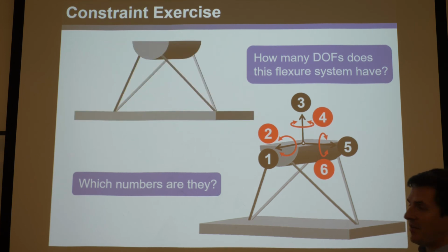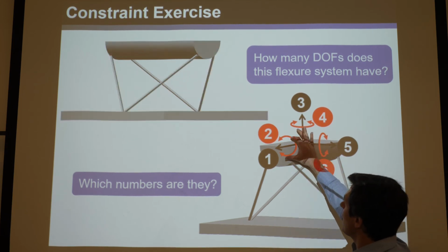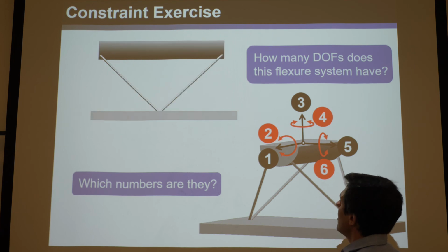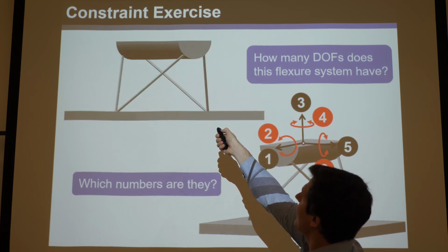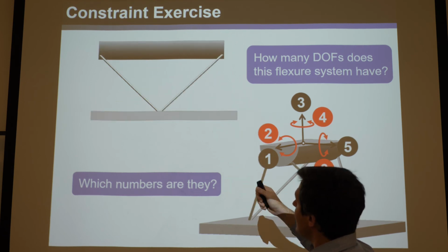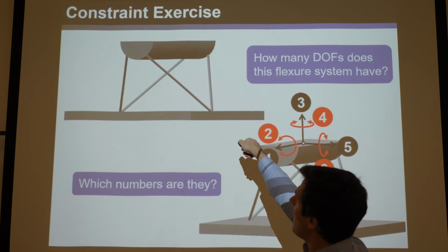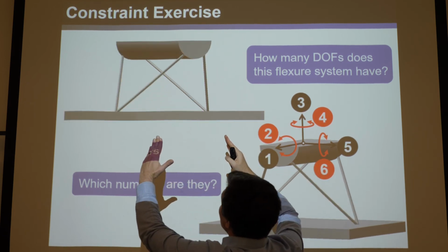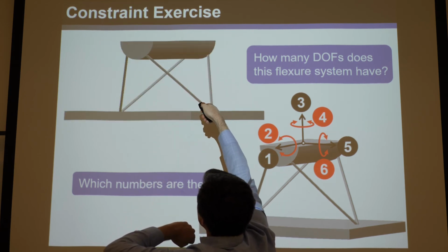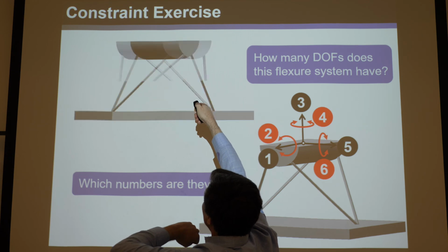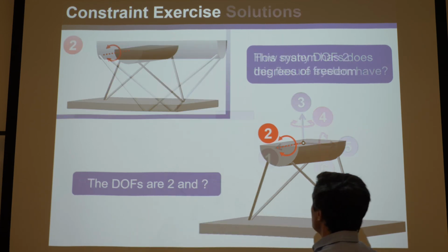Okay, so gee, we're down to the wire here. We're supposed to have 2 degrees of freedom, but we've only got one more option. Can we rotate around 2? Well, check it out. 2 would be right there at the top. And if you see, that is the instant center of all 4 of these guys. You can see they all align and go right up to where that is. So sure, it can do that one.